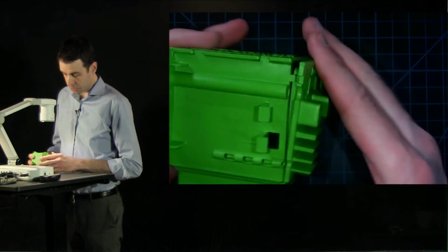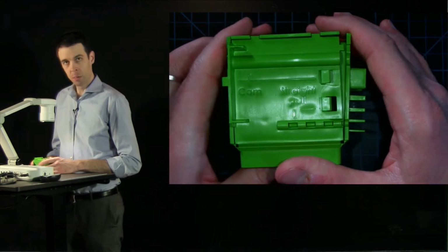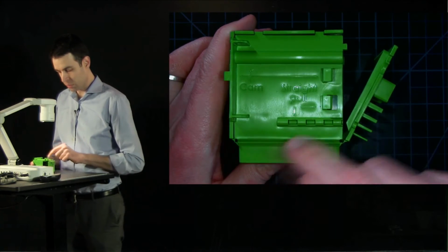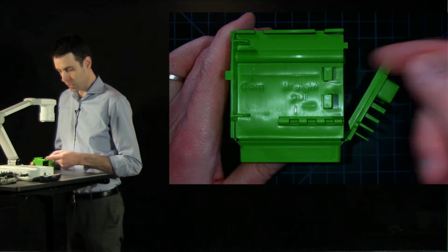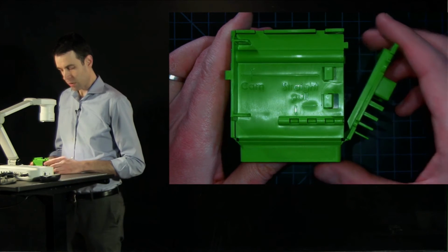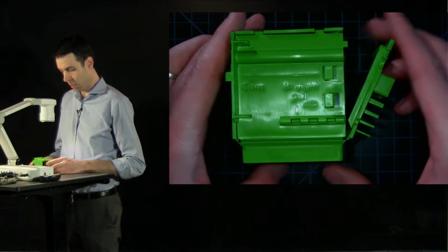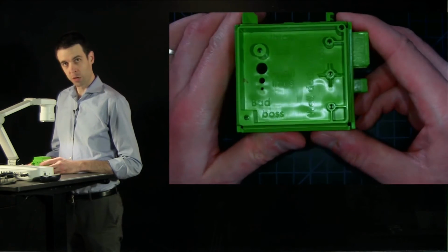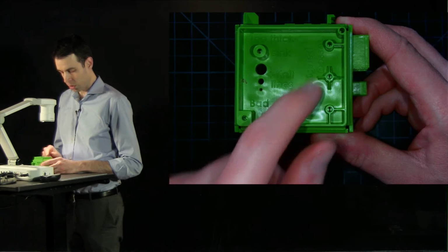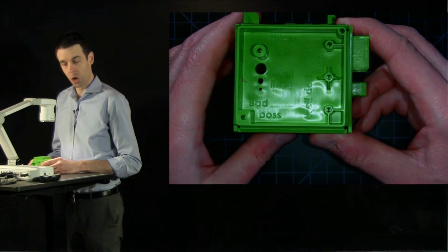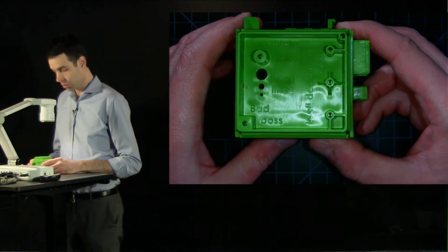We can't get through all the features in the time we have, but on this face there are some more complex features that represent, for example, side action, buried features where you need a third direction of action to be able to mold the part. There are also examples for different kinds of bosses, raised features, and how you can mechanically support them using thin walls so you don't create features that are too thick.